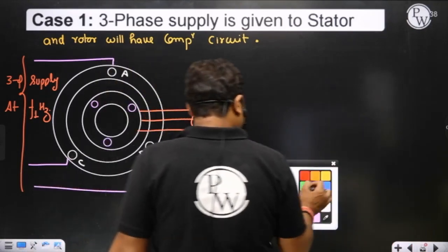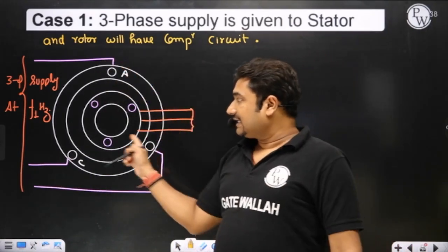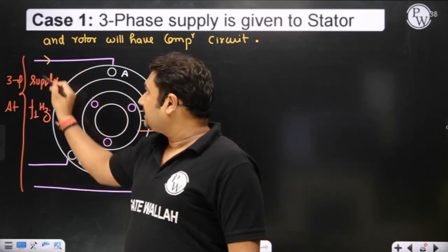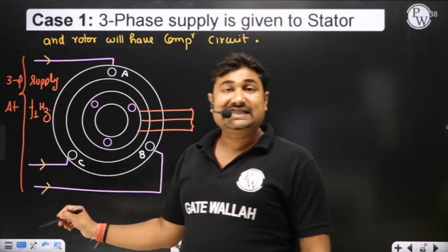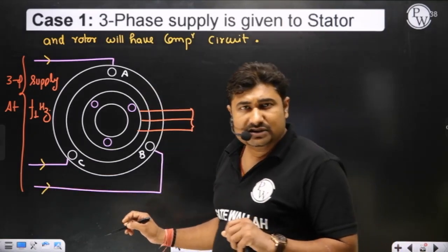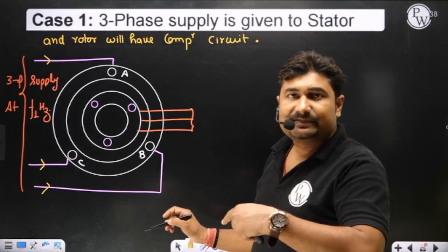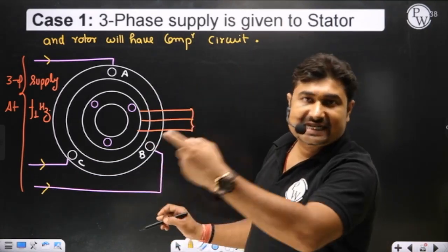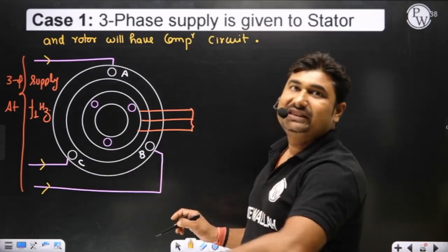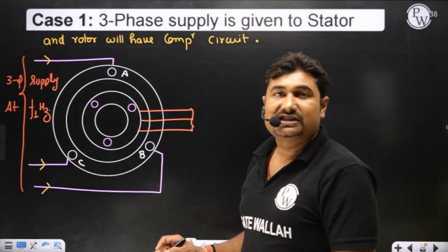We all know that when a 3-phase stator displaced in space by 120 degree is supplied by 3-phase current displaced in time by 120 degree, then a rotating magnetic field is produced, which rotates onto the stator body, in the air gap at synchronous speed.